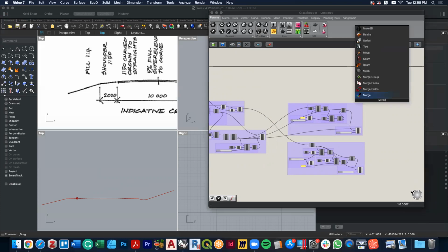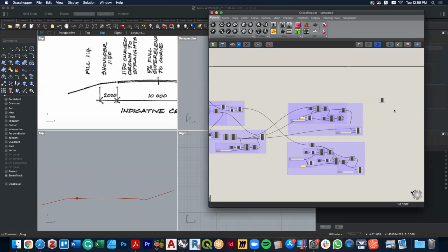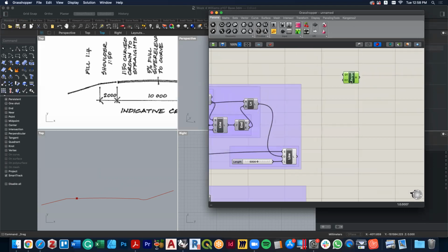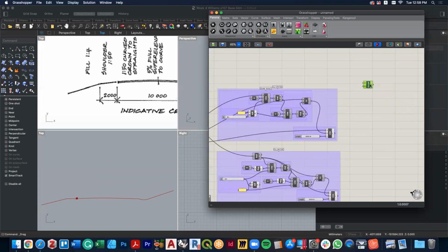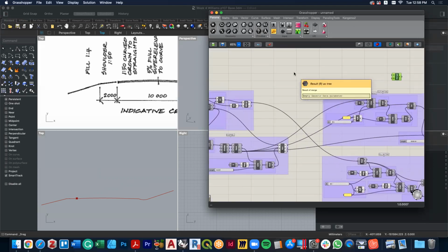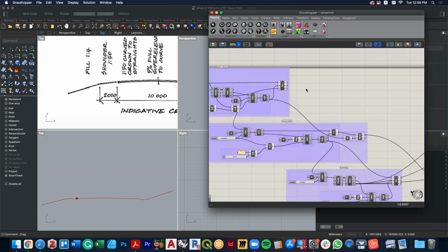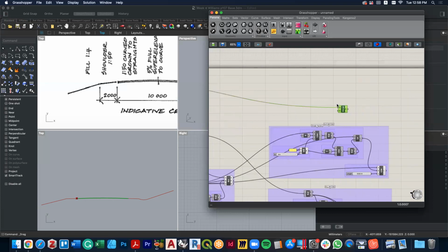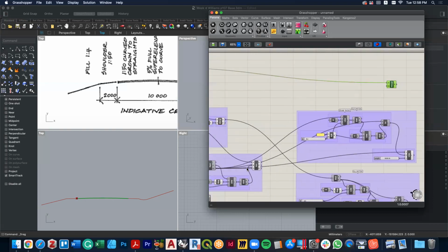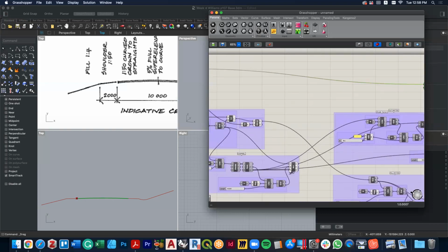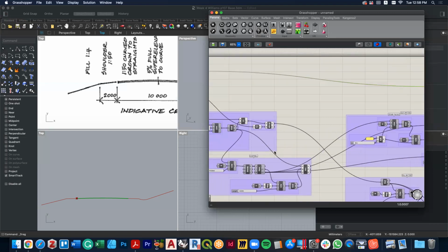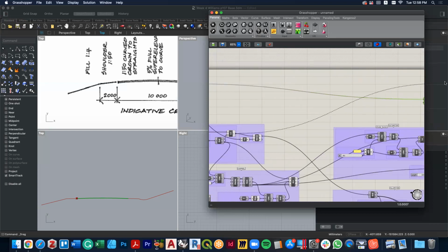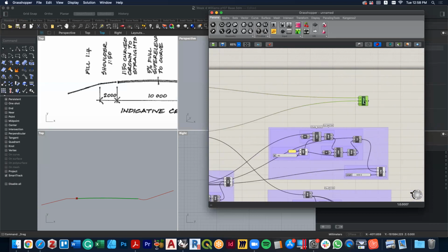And so I do that by using the merge command. What I do is basically like plugging the finished pieces of everything into each other. So I'm going to start by merging that arc, which is the road surface in there. Then I'm going to merge, it doesn't really matter so hugely, but I'll take a common sense approach. I'm going to then merge this component in there.